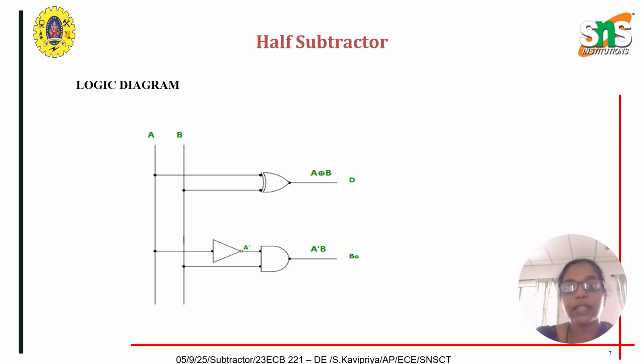So A and B are given as inputs to the XOR gate. In the output, we'll be getting the difference. For borrow, we give A to an inverter, and the output will be A dash, which is given as an input to the AND gate along with B, and we'll be getting the borrow.